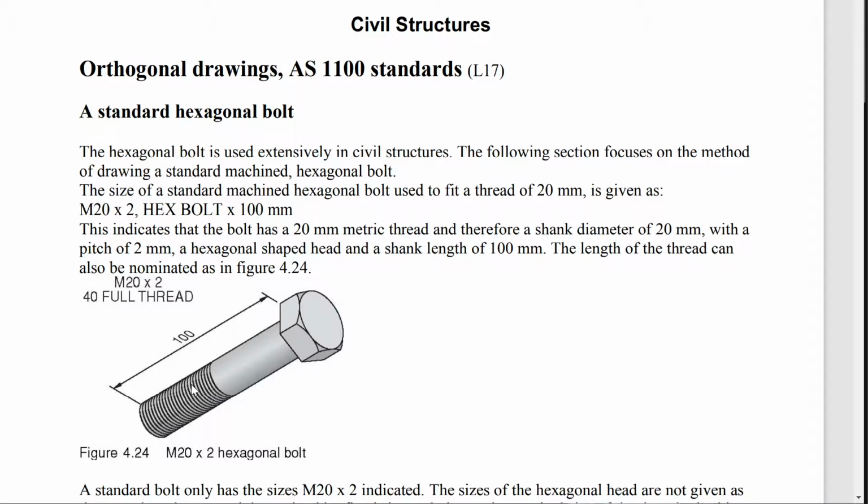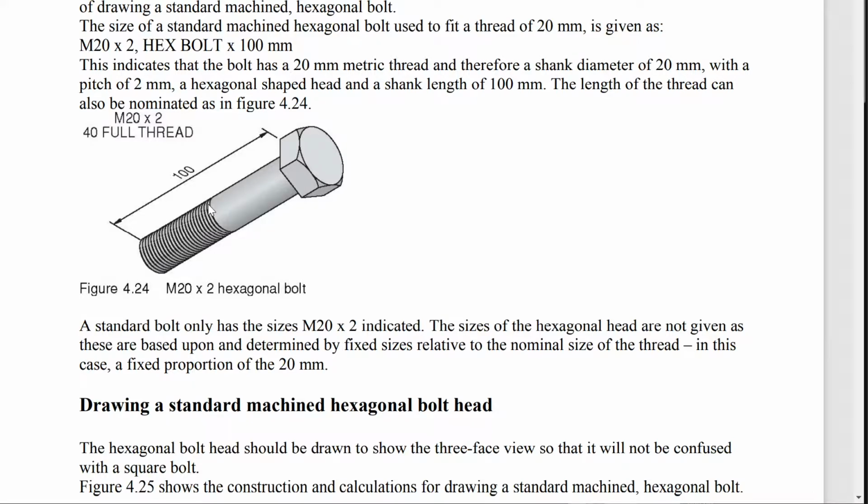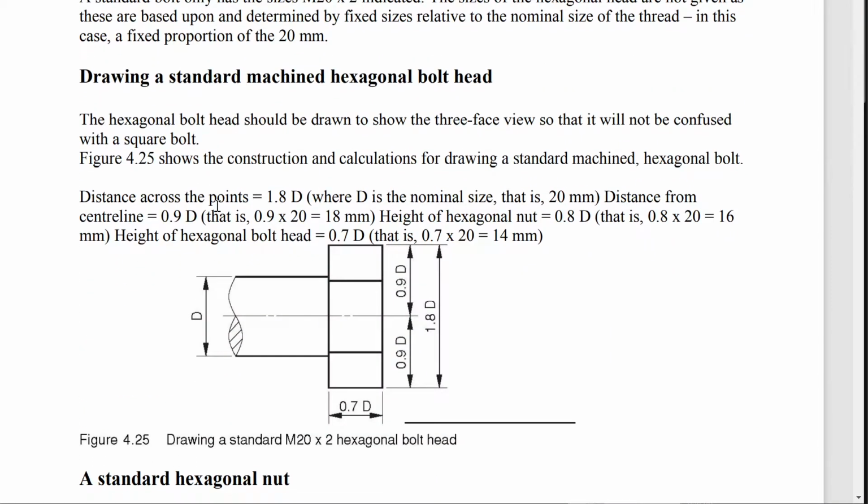When we draw a threaded section, we don't draw it as a zigzaggy line. Instead, we have a different standard that we use to draw nuts and bolts. So that's really important. Then there's the concept of what is a section, right? So sections are fairly important. We use sections to show things that are cut in half. Now, we never section bolts, along with a couple of other things that we never section.